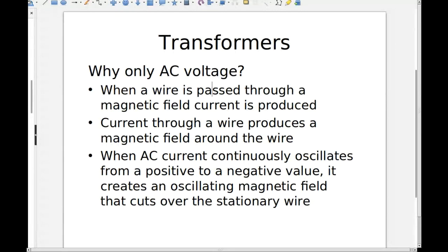So you've got to keep the magnetic flux changing. If you remember, in DC, if we pass a DC current through an inductor, we just energize that core, and then it just looks like a short circuit. So we've got to keep that magnetic flux changing to use this transformer.